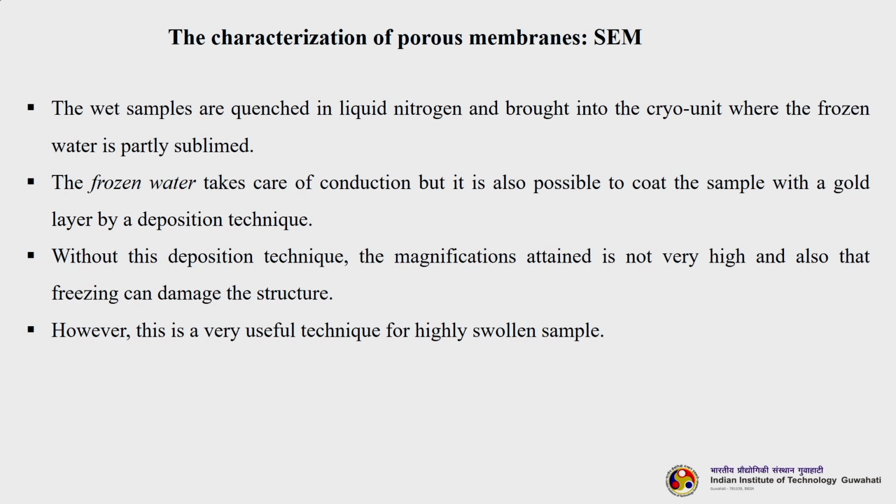The frozen water takes care of conduction, but it is also possible to coat the sample with a gold layer by a deposition technique. But coating by gold layer is a time consuming as well as costly process. However, it is done if you want a particular image without any hindrance, no artifacts, nothing, then it is better to coat with a gold layer.